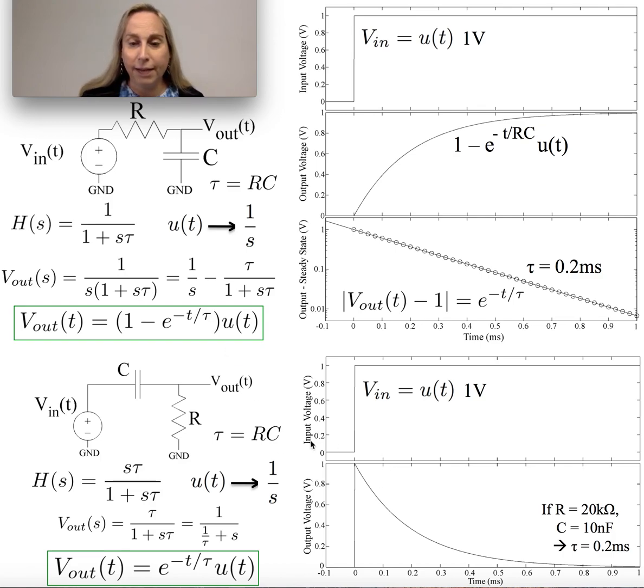Well, if I look at it for the high pass structure, and it's a high pass because we're going to be emphasizing the steps, the changes, the rapid parts of it, and not the lower frequency components. So if I put a step in, I get an immediate response, and it's an instantaneous response. Basically, as I put a voltage change in V in initially, V out has to follow pretty much immediately.